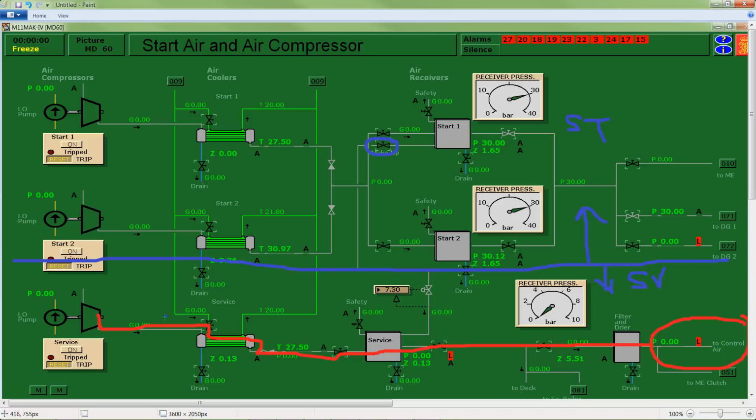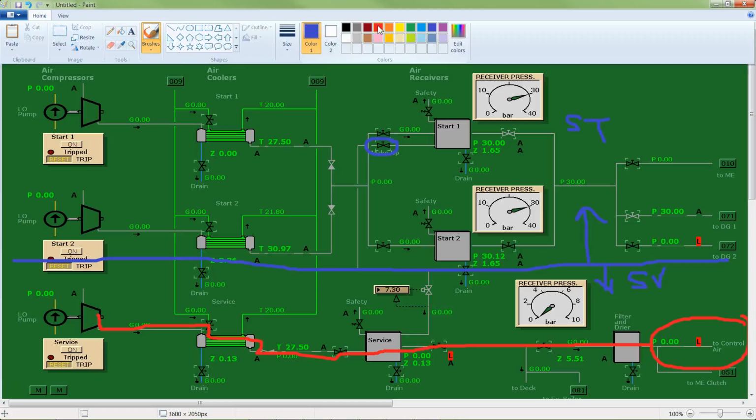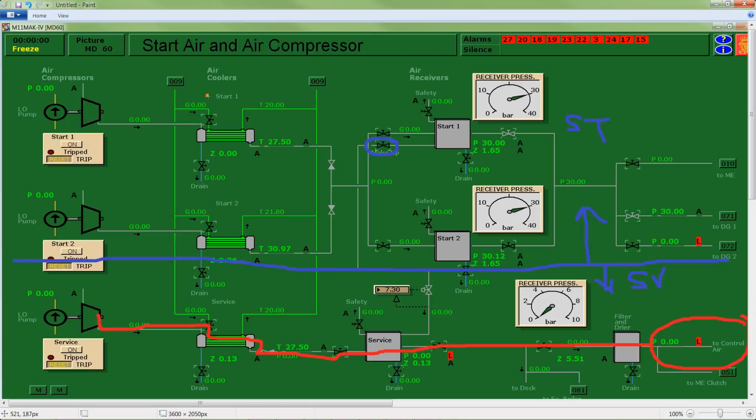What we also need to get set up, though, is our system here. We have this green system, which is our cooling water system. We've got this loop that we need to create for cooling water. So before we get our air compressors going, we want to make sure that we have water that's available for cooling. So let's go through those steps.